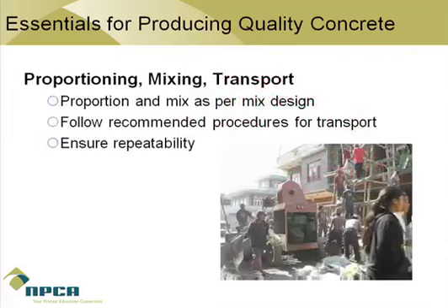During this course, we will go into proportioning, mixing, and transportation of the concrete. Following the specified mix design may be easier now than it was 20 years ago due to automated batching systems, but it's still important to monitor all quantities. Also, many plants have multiple mix designs, as high as 30. The right mix design for the job is key. Allowing adequate mix time, but not too much mix time, is essential.